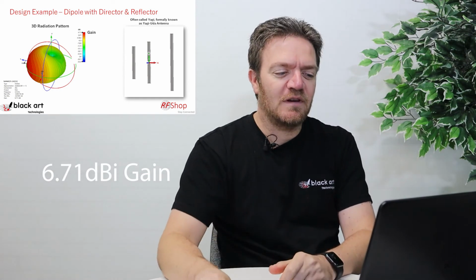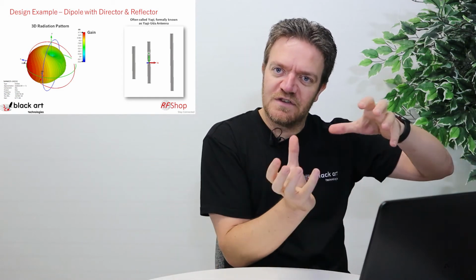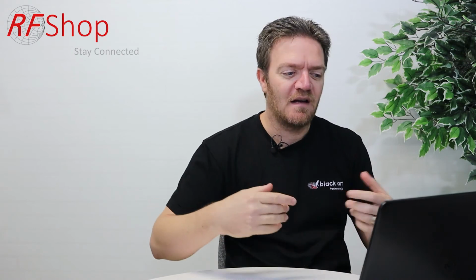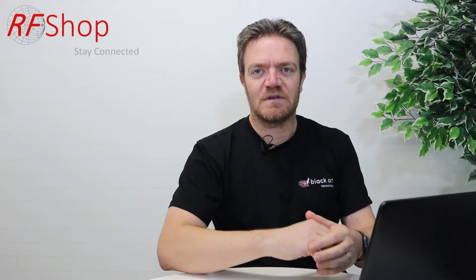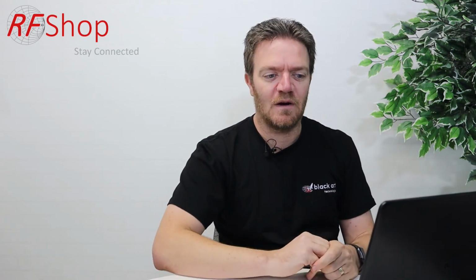If I move to the next screen, you can see where I had something that was going all around, then I started to sway more energy towards one direction. Now it's getting even more pronounced that my energy is going much more in one direction and much less to the back. And that is how you design antennas. That's what you do in antenna design. This is one specific example, but that's what we do. We basically start to manipulate the radiation pattern to what we need and what we want.